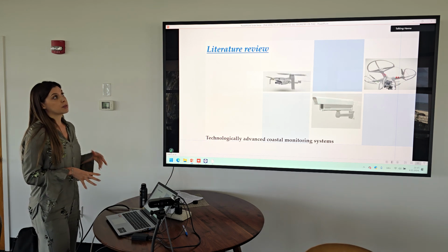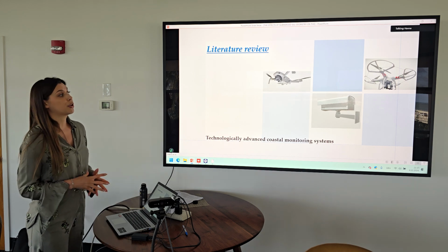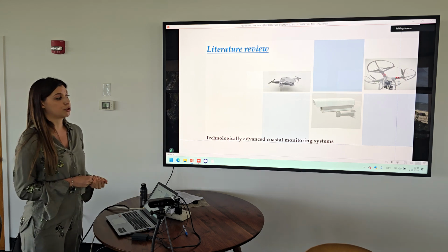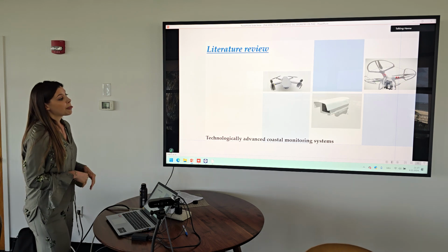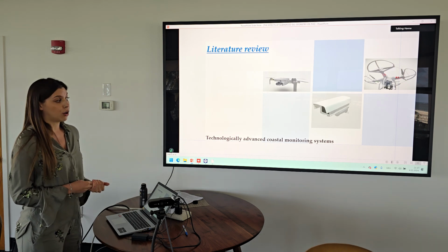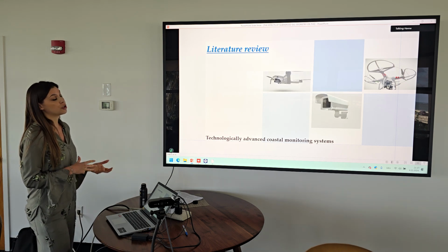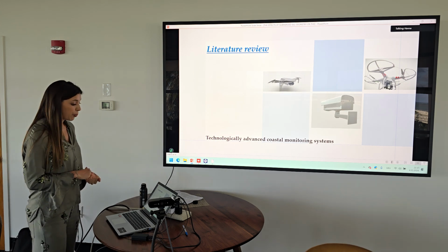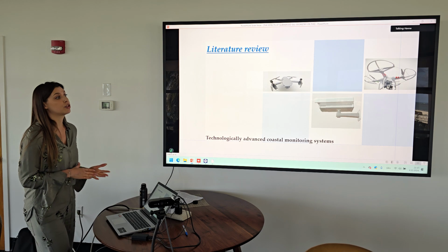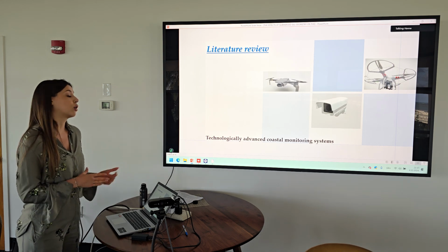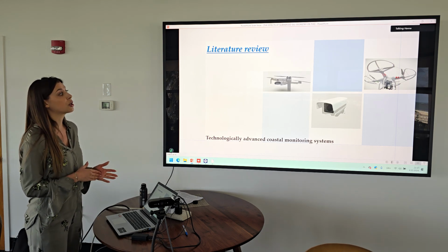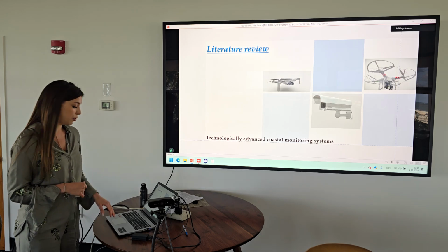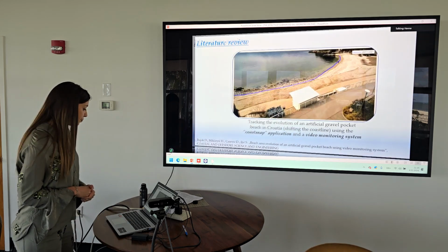Coastal monitoring systems based on photogrammetry, video monitoring systems, or drones enable the creation of a high-resolution 3D model of the beach and tracking of morphological changes. In addition to that, using these techniques also provides a clearer picture of advantages or disadvantages of constructed hydraulic structures, including their geometry and position, which contribute to the behavior of the beach.